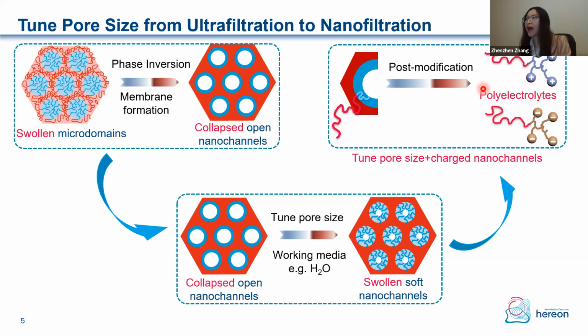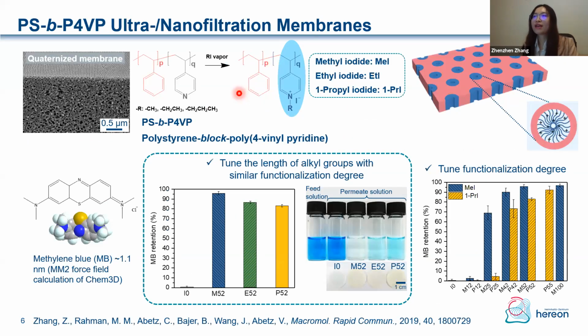Based on those, we can post-modify the polymer chain within the pore nanochannels to introduce the polyelectrolytes and then tune the pore size. In the meantime, we also introduce the charged functionality. Based on this idea, our first study is to use the polystyrene-block-poly(4-vinylpyridine) membrane.